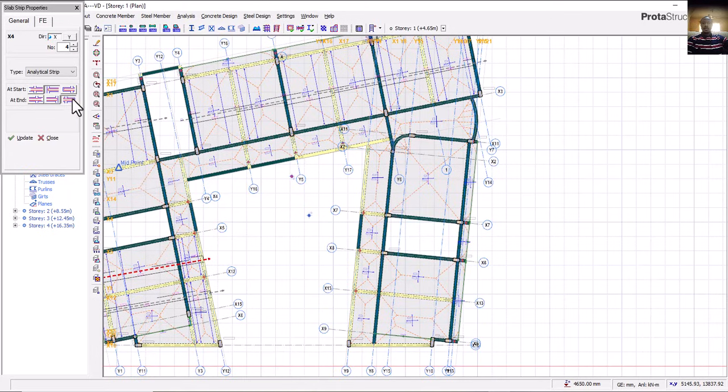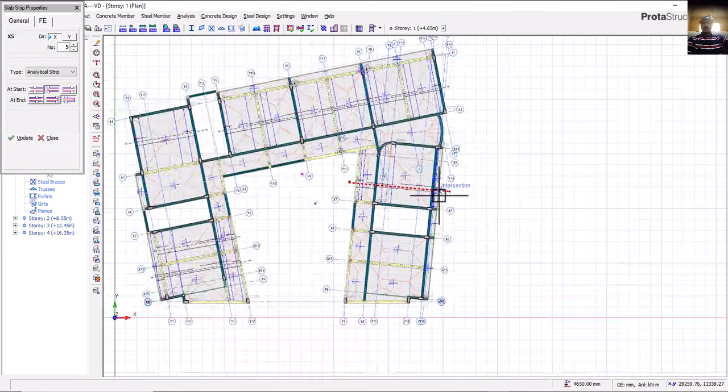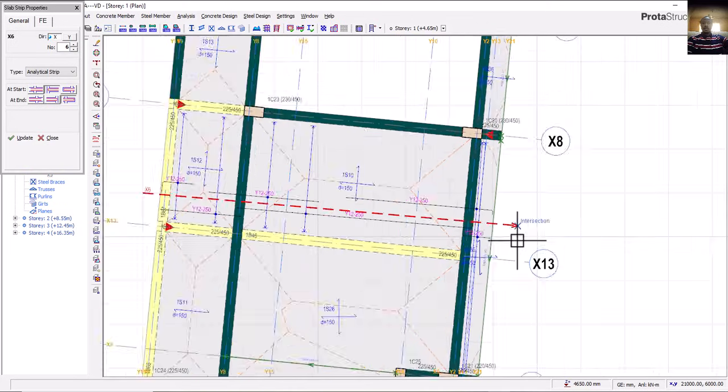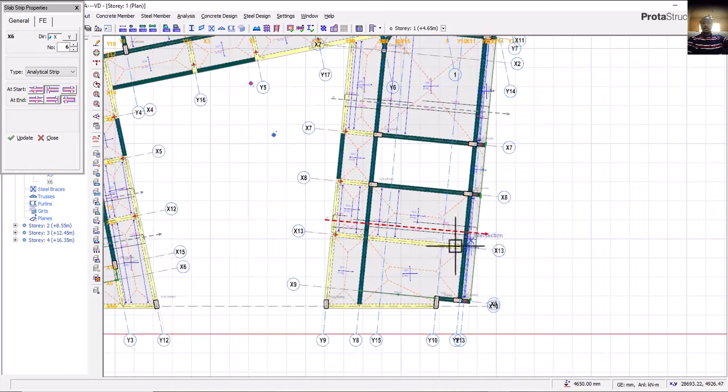All right. So I'll come here now, from cantilever to beam. You can see that my Y direction is active. I'll come here now. From here, I also come here, then click. Correct. So it's still passing. Very good. It's passing at Y12 at 250, which is okay, and that also represents this one.